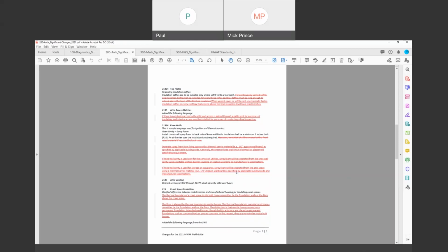So, Paul, if we were looking at insulating one of those, we could weigh the options of getting in and dense packing or insulating the floor. I don't know if we necessarily hit dense pack level, or we could just address the foundation wall. Correct. I would always pick the foundation wall if I were the installer, but there is an option to do it either way. Right, that's what I'm saying. It's just like a site built home at this point. You have the option of the foundation wall or the floor. Okay. Crystal clear.